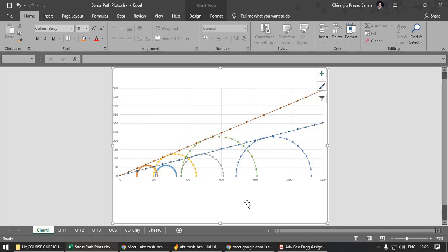If the stability is really at stake, we have to take precautions if such a situation arises where there is shearing at a very quick rate, and there is a significant amount of pore pressure generation, and it is totally undrained shearing. So in those cases we may need to consider it.